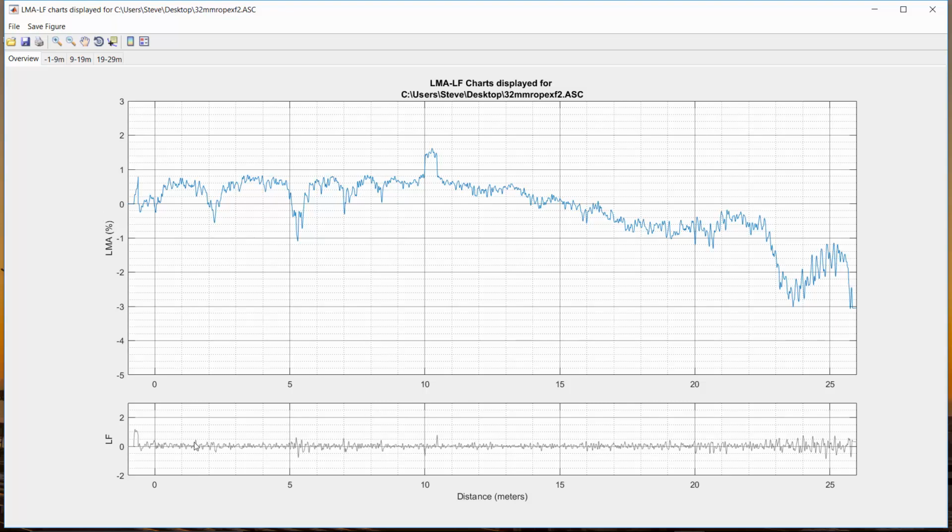Note that the scale of this plot is arbitrary. The LF signal is qualitative only and cannot be calibrated. Therefore, it cannot be used to determine or estimate the number of external or internal broken wires, single and in clusters, and the severity of corrosion pitting. As a consequence, it cannot be used to make rational rope retirement decisions. This has been amply demonstrated by impartial and independent round-robin tests. I want to bring your attention to this save figure.